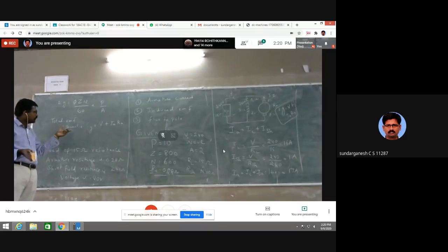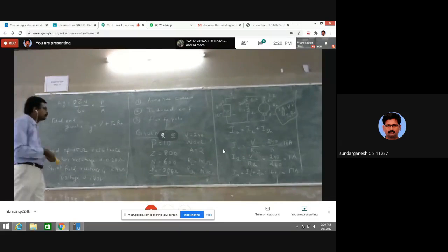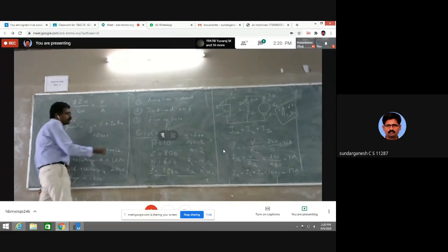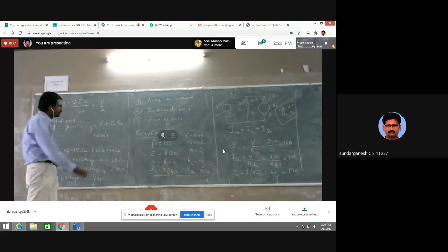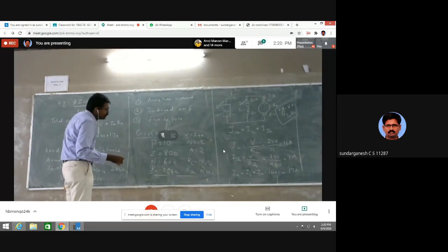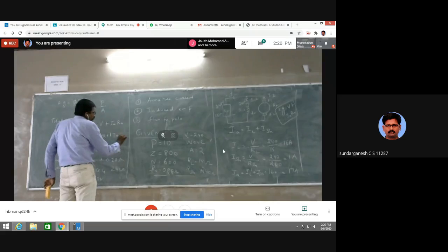Total EMF generated is equal to V plus IA RA. V you know is 240. IA we have found is 17 amps. RA they have given as 0.2.